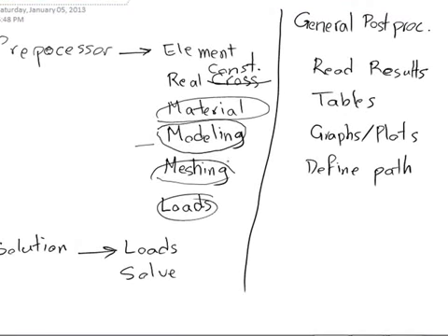I'm just going to be staying in the simple side of the explanation and just tell you that there are nodes and elements that ANSYS needs in order to be able to do the analysis for you. And that's the task of meshing. So when you do modeling and you create areas or volumes or lines, then you use the mesh to divide your model into a number of nodes and elements for ANSYS to be able to do the analysis.